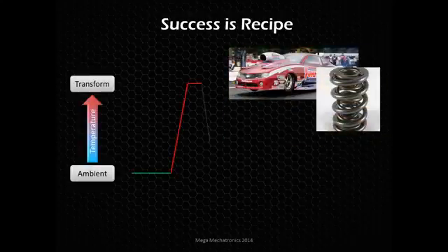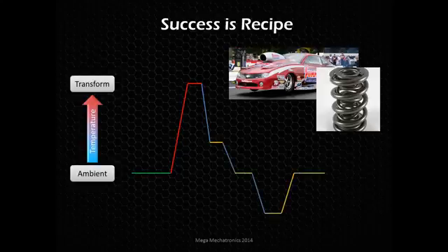So again, looking at this chart, an example process for a high-performance valve spring would look something like this, where there's a hardening, there's an austemper, where we're not bringing that all the way down to room temperature, and we're not quenching it, and the quench rate is a little bit slower because we're dipping that in some molten salt and holding it at a higher temperature.